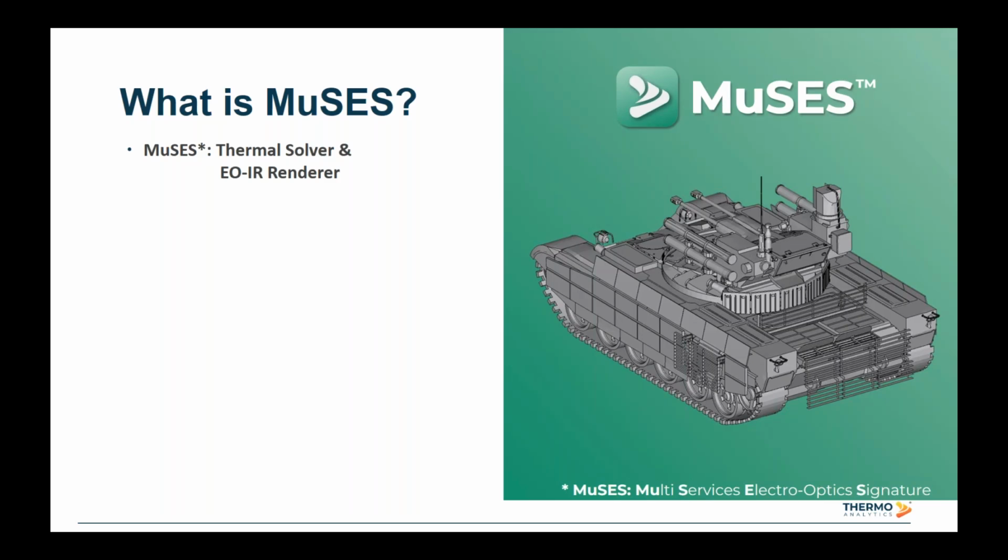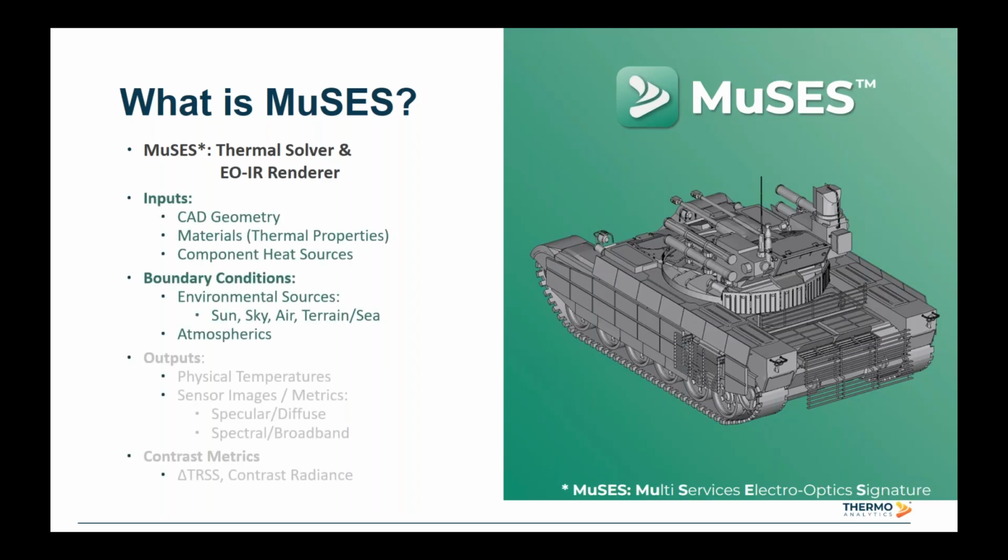But at its core, MuSES is both a transient thermal solver and an EOIR rendering tool. And so the inputs to the tool are going to be 3D geometry in the form of a surface mesh, a description of the materials along with the thermal properties of those materials and what parts of the geometry they're applied to, and heat sources for various components, which might include engines, exhaust systems, electronics, and so forth. Then we apply boundary conditions, and that's going to be things like weather for terrestrial applications, and atmospherics if it applies. So that's kind of the inputs.